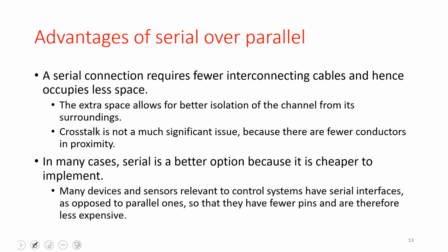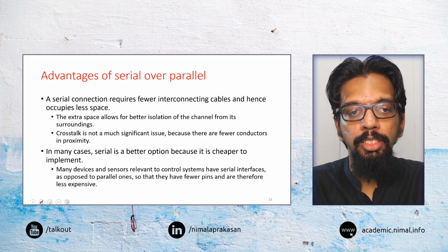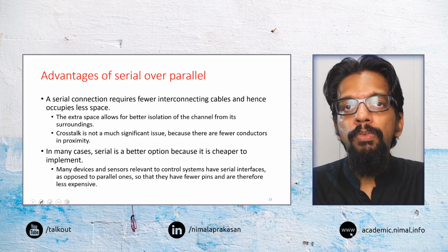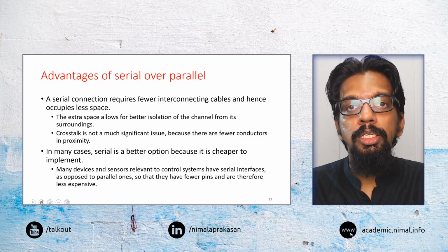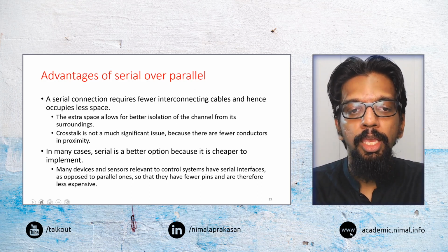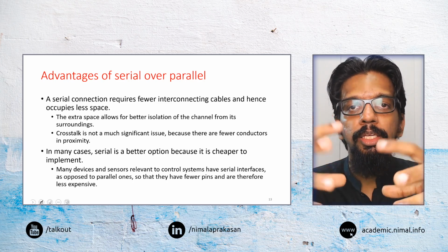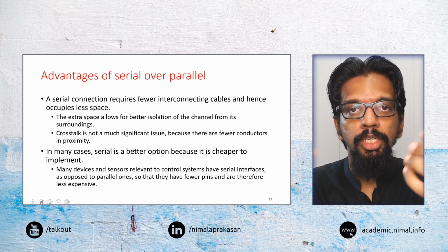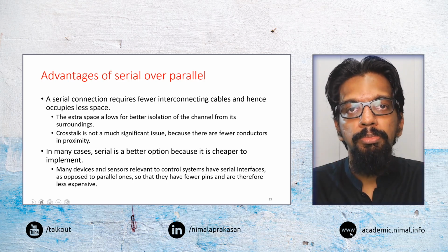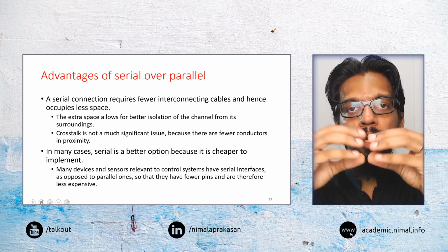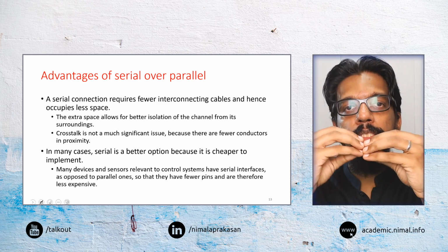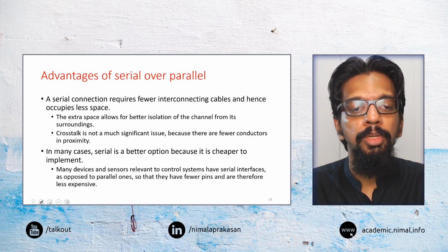So with that, if we think about the advantages of serial communication over parallel communication, the main advantage is serial communication requires few interconnecting cables. So it doesn't require many cables to do the connectivity. It can essentially work with one or two wires, maybe a few more, but significantly fewer wires compared to parallel communication.